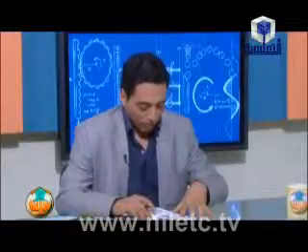And also compare between the N-type and the P-type with respect to the type of charge carriers. We know the difference between N-type and P-type; I explained before how to increase the conductivity of a semiconductor such as silicon. If we want to increase its electrical conductivity, there are two methods: first by heating, or by doping. In case of P-type, we dope the silicon with an element of the third group, and in case of N-type, we dope the silicon with an element of the fifth group. So this is the difference between P-type and N-type.